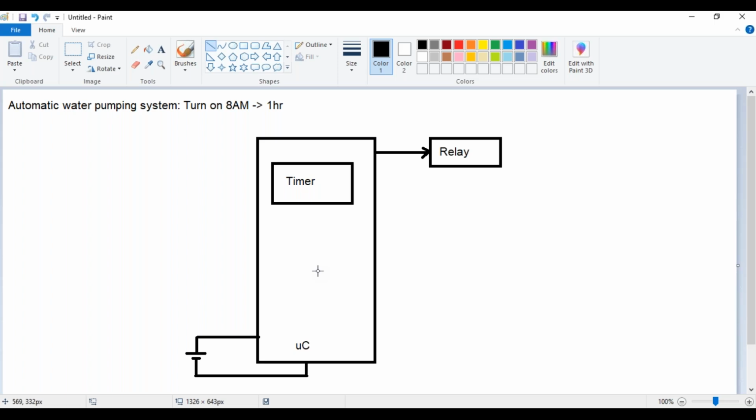So the whole system should actually be active for a duration of 1 hour only. Now in the rest of the 23 hours, can I put my microcontroller to sleep mode to save some power? Yes. But if I put my microcontroller to sleep mode, do you think the timer will still be able to count the time? I have taken a timer which is available inside the microcontroller.